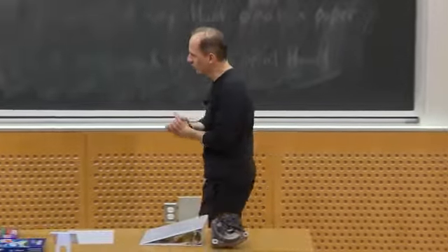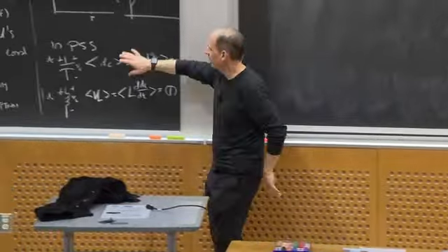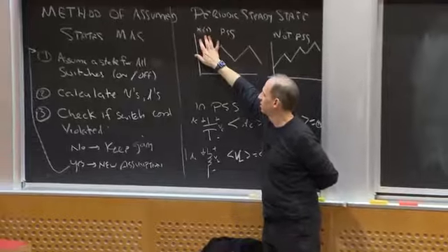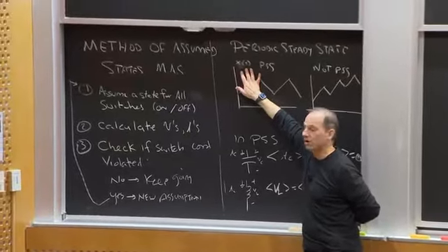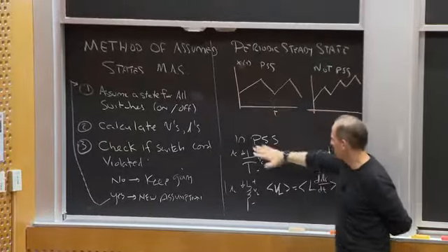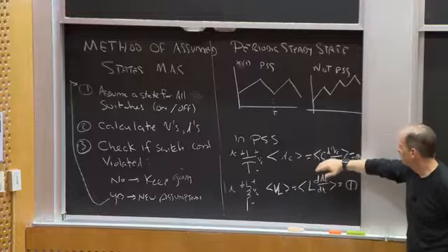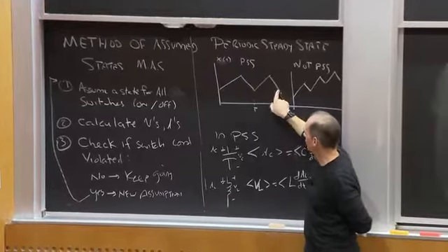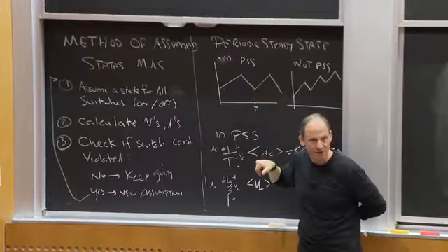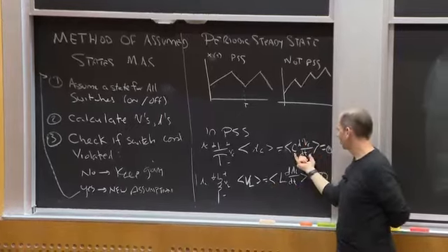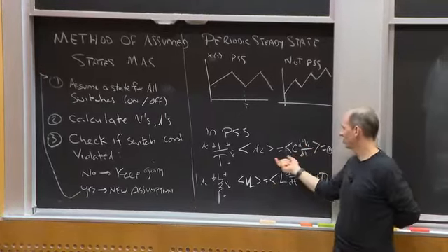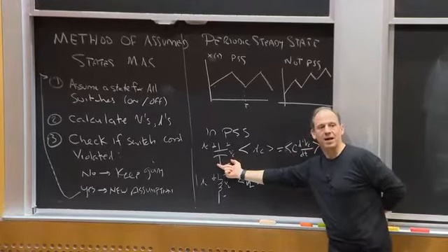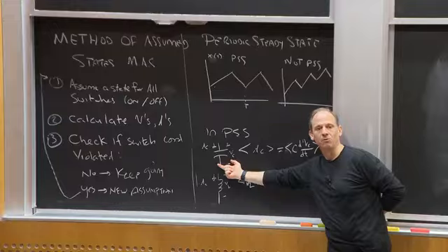That can help you figure out what the circuit's going to do or what it's capable of in periodic steady state. So for example, suppose X is a voltage in periodic steady state. We know that the average rate of change of this voltage is 0 because it's just going up and down. That means if it was a capacitor, because the average rate of change of voltage is 0, the average current through a capacitor in periodic steady state is 0.